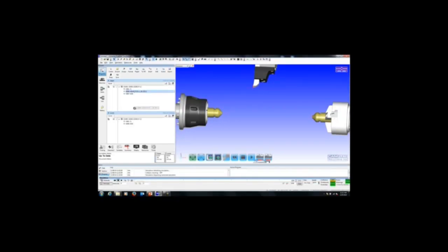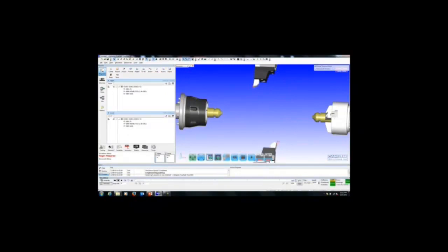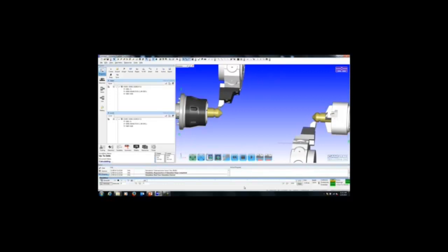Looks great. Now I'm going to take that toolpath and drag it to the lower turret. I'm going to copy it. I'm going to go ahead and reverse my X's and my arcs for the subspindle. And I'll go ahead and pick a tool position. And number 1 is open, so I'll go ahead and grab that. Camplete automatically updates the G-code for the other side lower turret. I'll regenerate it and test it. As I play this, again, I'm at 200% speed, but you'll notice that with the click of a button, I now have a toolpath on the left and the right, even though I've only generated a toolpath for that left side.